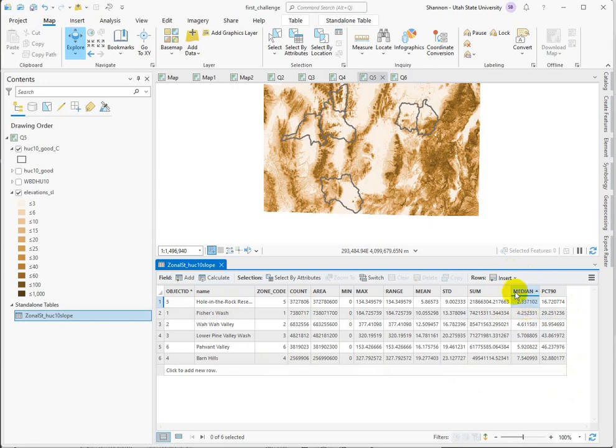But if you were to report this, is 0.1% a reasonable precision? I would say at most, yes. So 2.3% rise. You know, these values just aren't correct when we're dealing with a 10-meter DEM. We can go back to the DEM lab and look up the vertical accuracy for the USGS 3D elevation program data sets. But considering that we're taking a 10-meter cell that's already been interpolated and then running slope, we're going to get rid of all these significant digits responsibly.